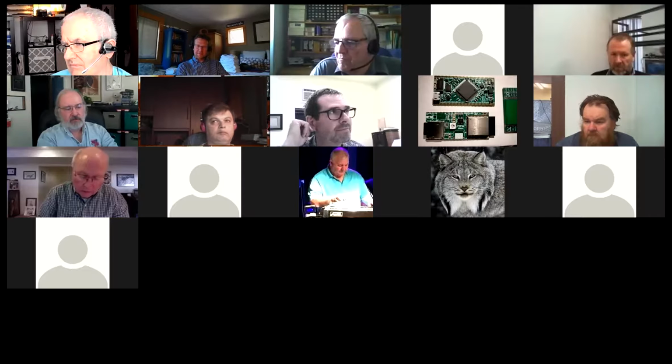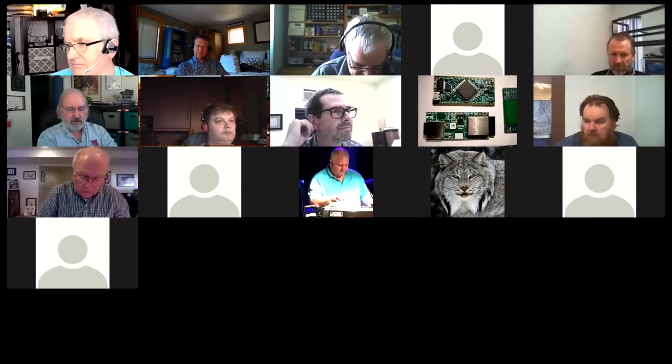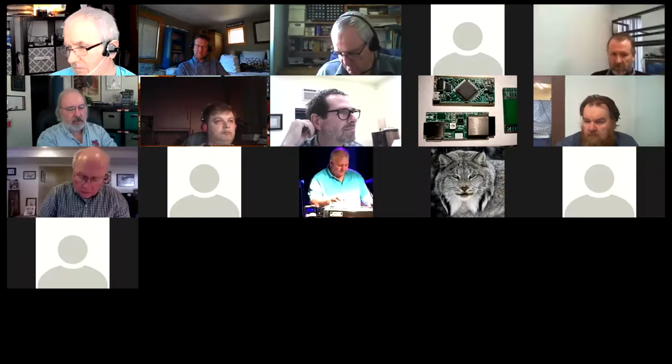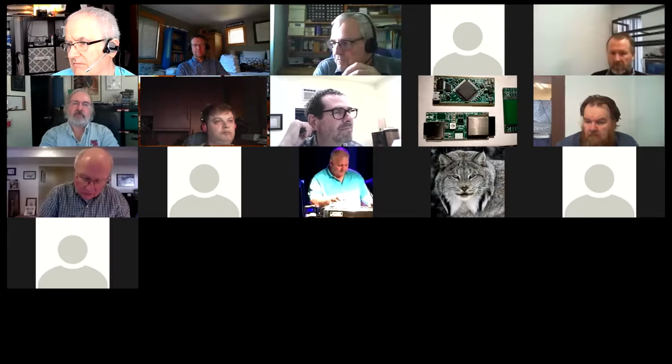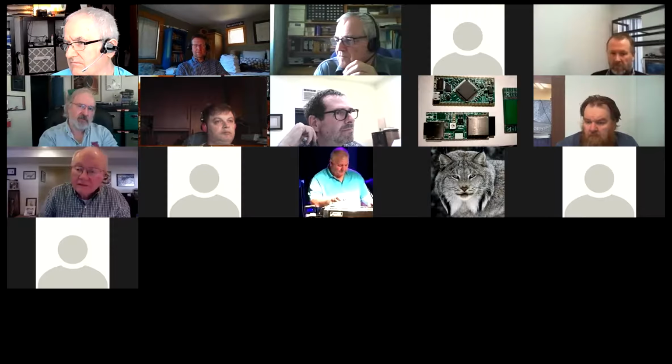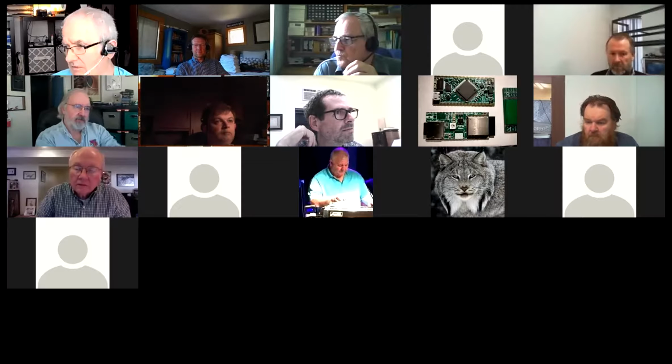Well, the whole idea is, one of the goals for my driver is that there are at least 4 different major chipsets out there for these panels. A lot of them are easier to clock than mine, but I'll put settings at the top of the driver so you can adapt it to your channel and your chip types. You'll also be able to adapt it to the geometry of your panel and of the collection of panels that you're daisy chaining. And so we'll see what we can do, right?